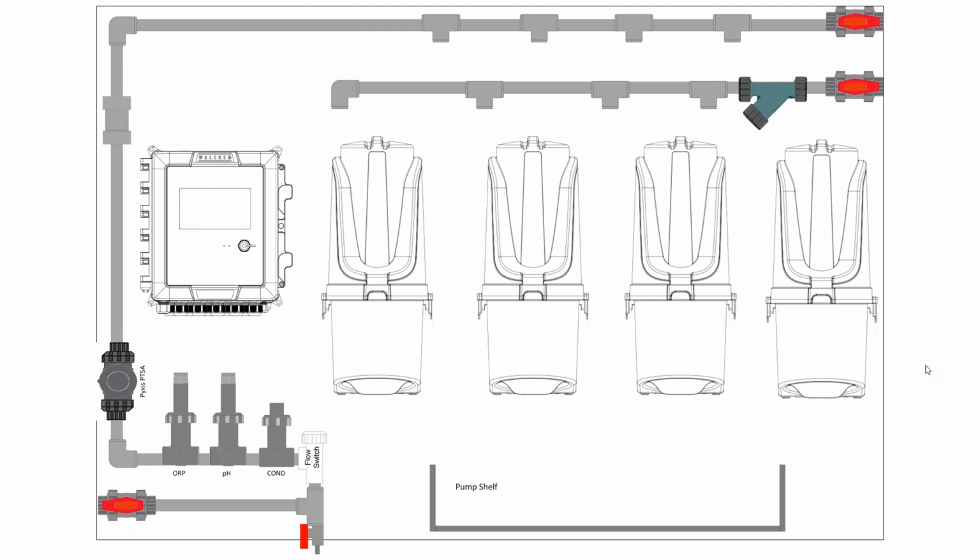Cool. Another question. In the event of float failure, is there any sort of secondary containment or safety measure that keeps it from overflowing out of the UltraM? I think the UltraM is pretty much sealed all the way around though, correct? Yeah, there's an overflow standpipe. Offset from the chemical solution outlet is a 1/2 inch female MPT port, threaded male to hose barb to 1/2 inch hose barb connection.